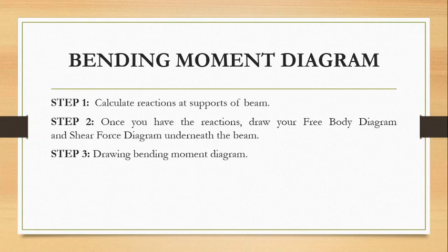In case we have to make that beam efficient enough for 30 feet, we have to increase the depth of the beam. By increasing the depth of the beam, we are actually adding more material to it, and there is a possibility that the same beam can collapse due to the shear forces present in it because of its own weight. And adding more material to the beam will cost us more as well.